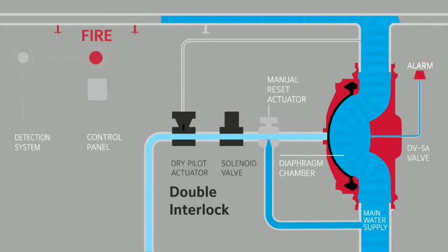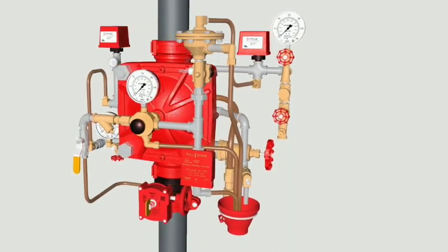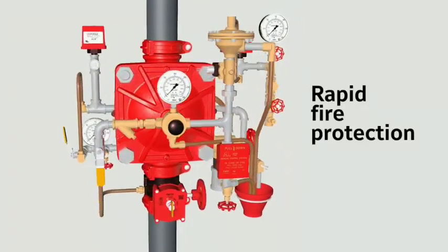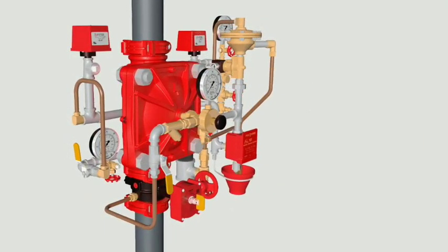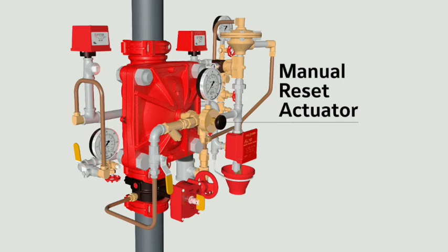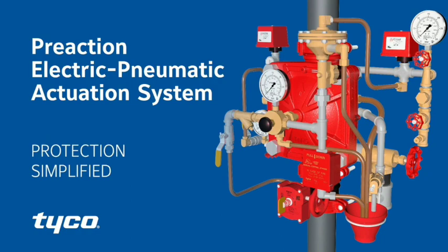Relays. A relay is an electromagnetically actuated switch. It is a simple electrical device used for signal processing. Relays are designed to withstand heavy power surges and harsh environmental conditions. When a voltage is applied to the solenoid coil, an electromagnetic field results. This causes the armature to be attracted to the coil core. The armature actuates the relay contacts, either closing or opening them, depending on the design. A return spring returns the armature to its initial position when the current to the coil is interrupted.